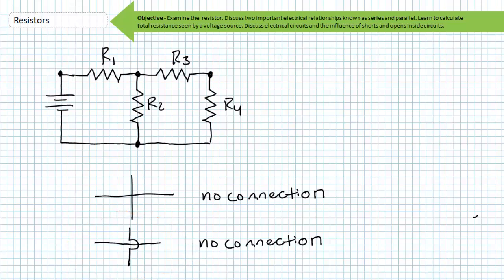Regarding the points of connection, these can also be numbered, lettered, or otherwise identified. The common term for these points of connection is the word node. You'll immediately recognize a conflict between component subscript notation and nodal notation using the same numerical identifiers. My advice is to deal with it. Consider this hypothetical scenario. Find V1. Does this mean find the voltage across resistor 1? Or does this mean find the voltage at node 1 with reference to some previously agreed upon reference point, like ground? I don't know. Seek clarification.